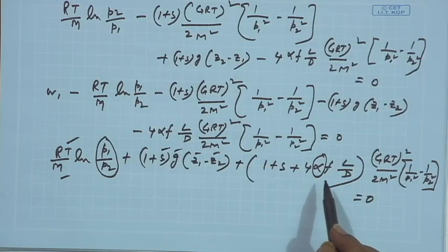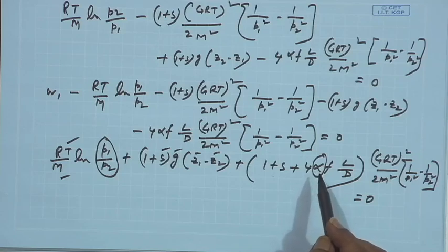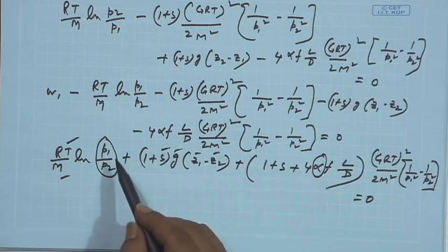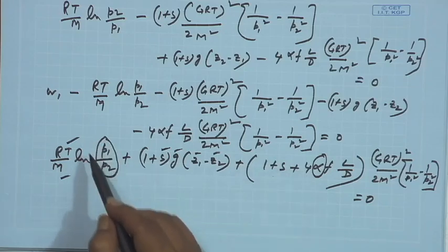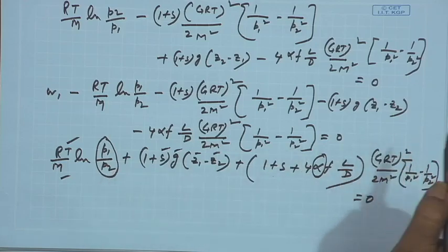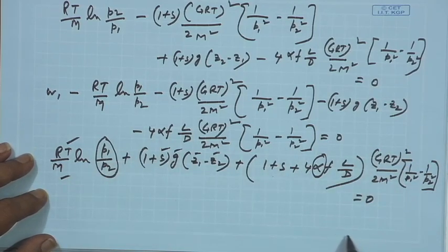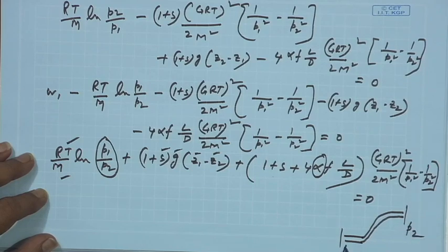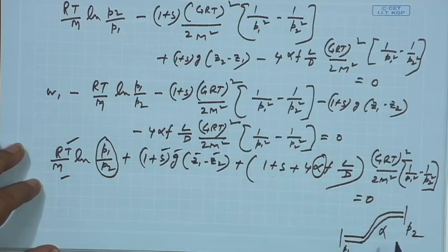So, that we are taking here also, that is the frictional loss. So, this alpha can be either known or unknown. The moment this alpha is not known, then you can play with that. If you know the pressure drops in the two places, like as we had shown earlier, if you know the pressure drop in the two places, from here you are conveying to that place, so this place pressures you know, P1 and P2, then for a known system you can find out the alpha value.